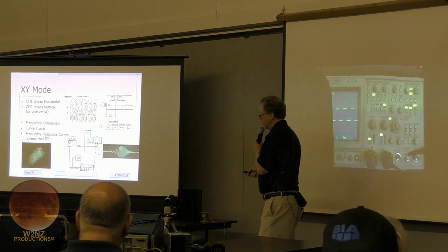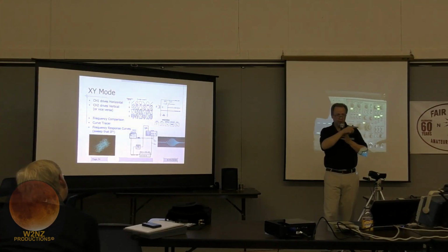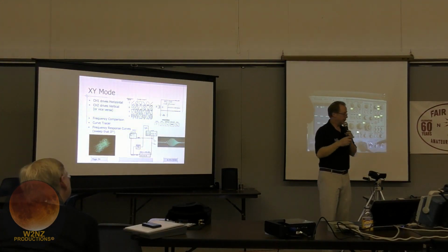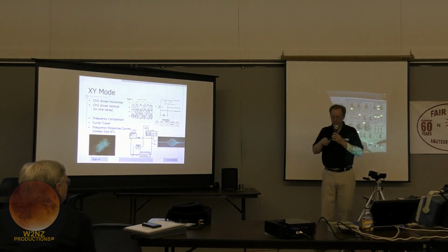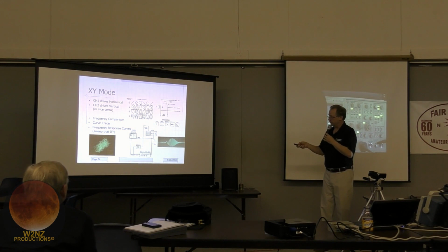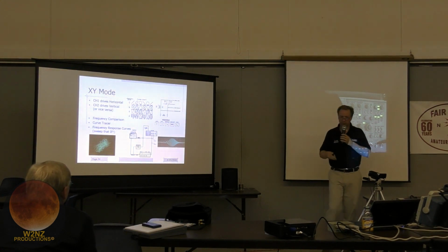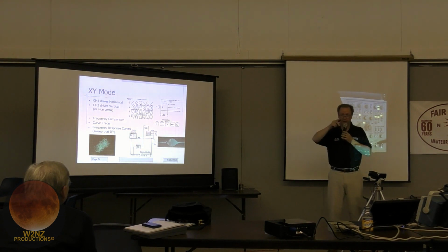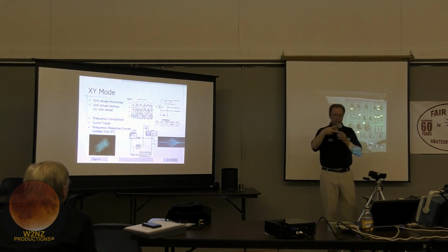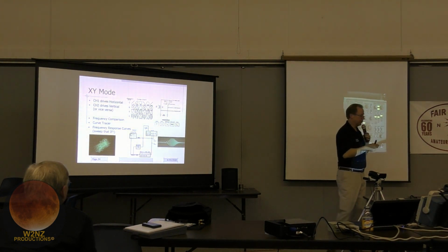Another thing you can do is a curve tracer. I want to do an IV curve of a diode to check the diode or something like that. You can actually drive the diode and measure voltage and current. This little circuit up here is often called an octopus. Take a look at this Google octopus tester. What it does is it applies a sinusoidal signal to a device under test, and you plot the voltage across it and the current through it, and basically create an IV curve tracer.